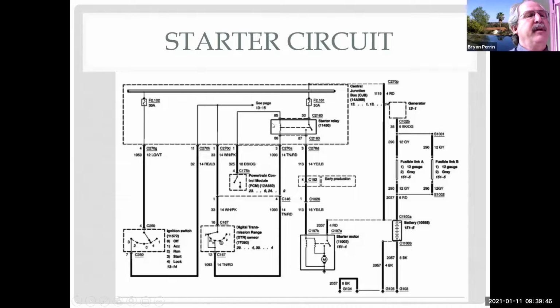And so if it does work, then we see the dash line over to the switch in the relay. The switch comes down and it's going to send power down to my starter motor. Now there's another solenoid inside here that creates electromagnetism and pulls this switch over, because this is going down to the ground side of the motor. Now I have battery power. It comes through this switch that we just closed, and now my engine's cranking over.